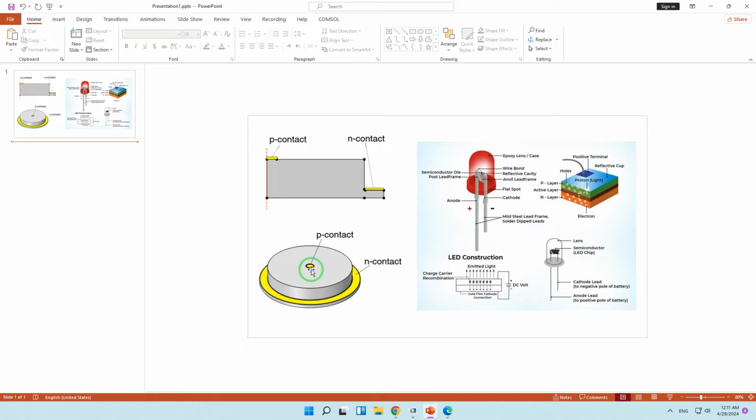And also we use the optical transition feature that allows electroluminescence to be calculated. This is achieved by clearing the stimulated emission checkbox within the feature such that only the spontaneous emission will be calculated. In the absence of any optical excitation from an incident electromagnetic field, the spontaneous emission will be the electroluminescence due to the carrier dynamics of the injected current.